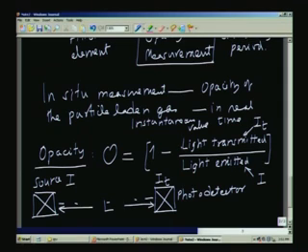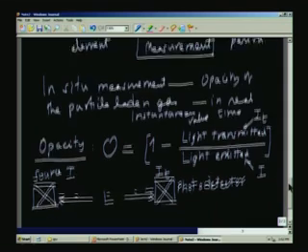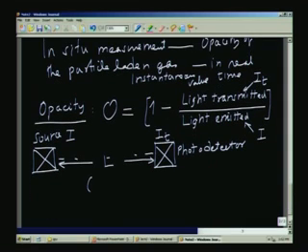So, 1 minus that, in other words, this is what is available at the end at the photo detector, that means that much has reached this place. So, this is the transmitted amount, it is nothing but 1 minus the transmittance. So, we can also define it as 1 minus tau, 1 minus transmittance. What is measured is the ratio of these two, and then you find out the opacity, and opacity can be a measure of the amount or concentration of the particulates.